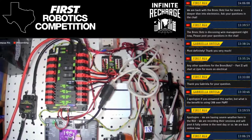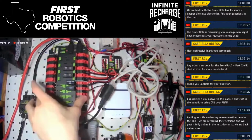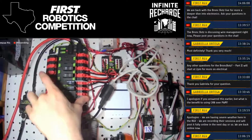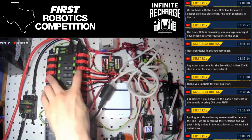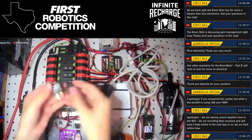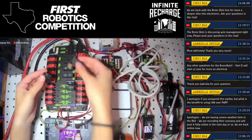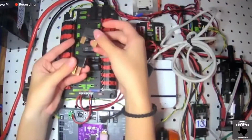So you can see here, what we were talking about in the earlier session, you've got these 40 amp and these 30 or 20 amp here. Obviously amp is again current. So if more than 40 amps tries to be drawn through these, the breaker will shut down the circuit. So here's a 40 amp breaker. You can see that they're significantly larger.